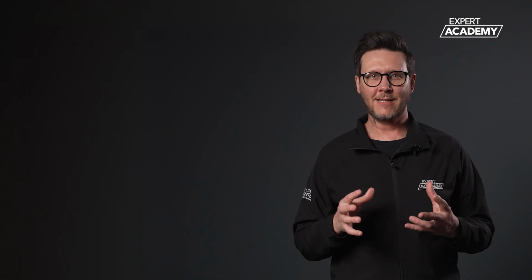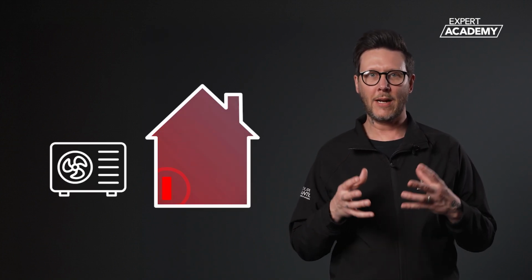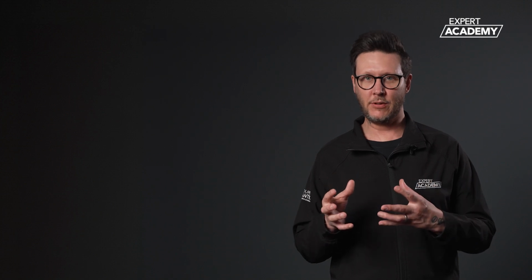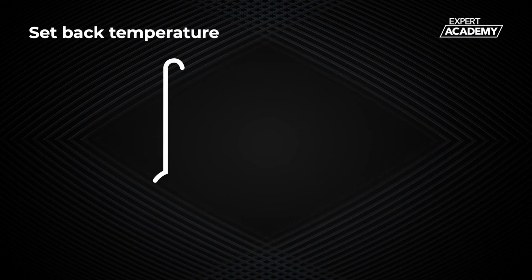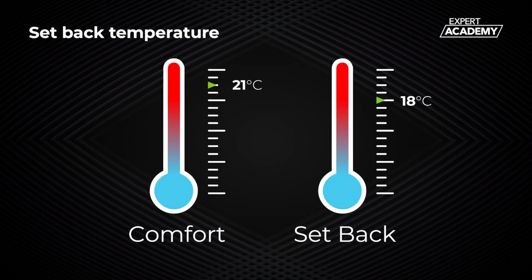Heat pumps are designed to be a continual heating source, maintaining the heat within a building. A good control will allow programming of desired comfort temperature and something known as setback temperature. It is more efficient to use setback temperatures in place of the off periods when controlling a heat pump. Common temperatures used are 21 degrees C for comfort and 18 degrees C for setback periods.